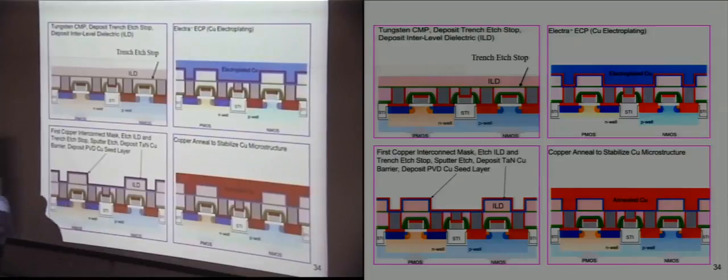Professor Puisi will be talking about RC delay in more detail. So this kind of interlayer dielectrics can be silicon oxide which is modified to bring down the dielectric constant and things like that. Okay. Once you put this interlayer dielectric, now you pattern the interlayer dielectric. So you can see that this interlayer dielectric is now modified. Now you start to deposit, you use the mask that is for forming the first copper layer. You etch your interlayer dielectric from the pattern.